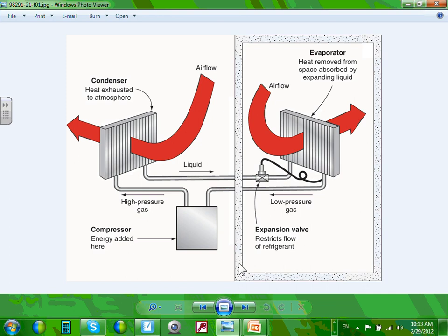HVAC equipment, yes sir. Can you go higher in horsepower? Yes, but you will be throwing money out the window. For example, if a disconnect is rated for 10 horsepower, would it handle 25 horsepower? Yep, absolutely. Same thing: if a disconnect is rated for 60 amps, would it replace a 30 amp? Yes, as long as you don't have a fuse in it. The fuse is a different story. You can't go higher on the fuse. If you need a 20 amp disconnect and you put in 30 amp, you overkill.